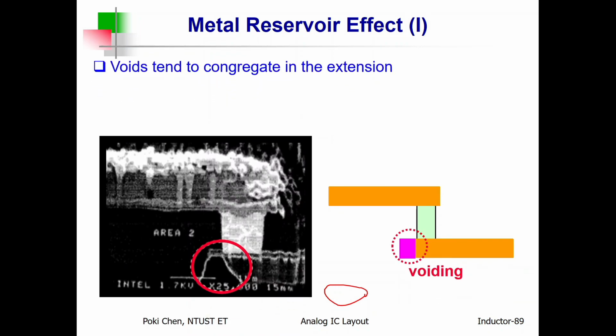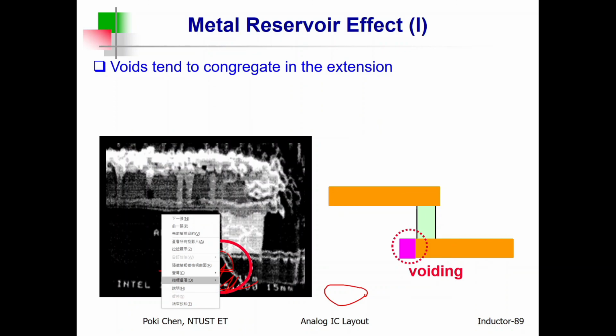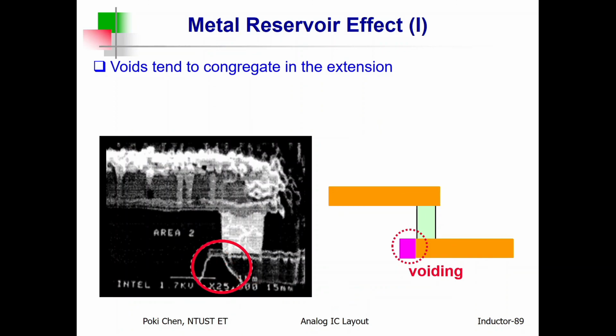Okay. Anyway, that is what you need to do, because from the beginning of the microphoto, you can see this portion become void. It becomes empty, right? So to solve the problem, you need to have extra layout here. That's it. Some kind of expansion for such kind of metal 9. A very simple idea. After you know the cause, and then the cure is very simple, right?